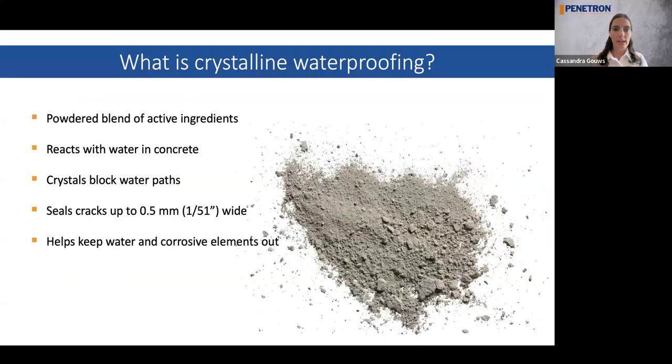It is a powdered blend of active ingredients that you incorporate into your concrete either at the batch plant as an admixture, or you can apply it as a treatment onto existing concrete. But either way, once it's incorporated into your concrete, it reacts with water. So water is the catalyst. And once it is exposed to water, so your concrete is cured with water or it rains after the fact, that water activates the crystal growth process.